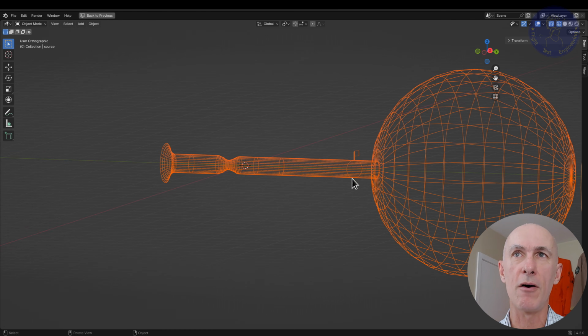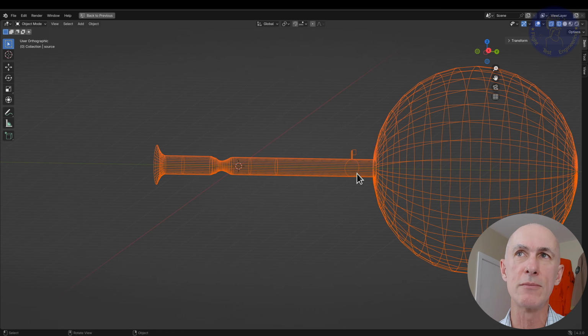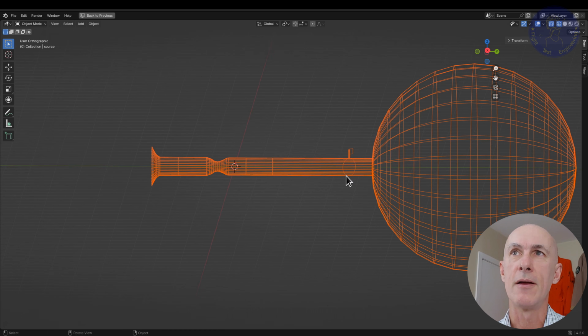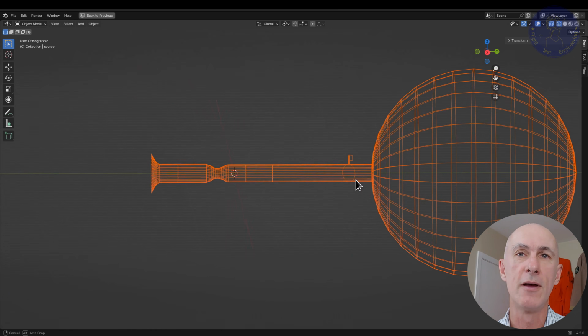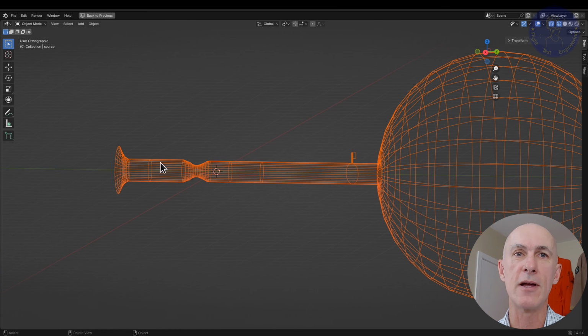As we open the valve and the flow starts, for now, let's just assume that there are no losses here. And in the tube, no boundary layer effects, no heat transfer, etc. So the flow starts slowly with pressures close to atmospheric pressure all along the tube here. And remember, the low pressure end is the vacuum chamber. Everything else is in the atmosphere here. As we open the outflow valve more and more, the flow will increase its velocity. And it's fairly intuitive to see this, that as you open here, our air particles are going to flow into the tube with more and more speed.